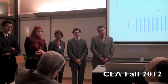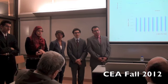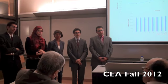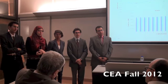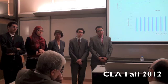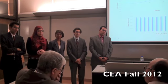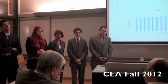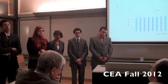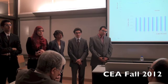We have a wind tunnel, and we did the analysis and the design review, and after we finished everything, while we were building this clock, the CFD gave us double the value of the wind. Double the value. And that was using ANSYS. So be careful with that, and try to check the results once.